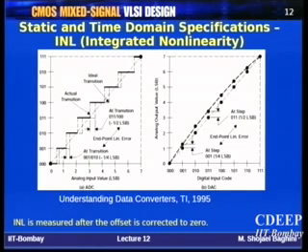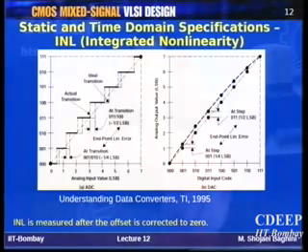Otherwise, whatever you measure and think is INL is actually INL plus offset. So first you compensate, and then you see how much your transition point, which was supposed to be, for example, at Vref by 4, which is 1/4 of your full scale, has been shifted by, say, 1 LSB, 2 LSB, whatever, depending on the performance you get from the ADC. So it is just a definition.